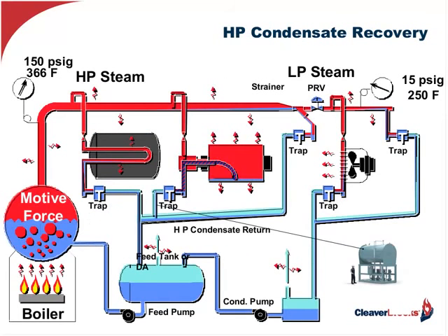Now, looking at this steam system, and again, I'm going to use this example of a corrugated container plant. So we've got a corrugator here. We've got our steam coming out of our boiler, and of course, as it radiates through the piping, even though it might be insulated, there's still a certain amount of radiation that takes place. We've got condensate that has to be trapped and returned back to the boiler room in the feed system. Now, we've got a siphon tube in this roller, coming off our single facer in our corrugator, and it's being trapped.